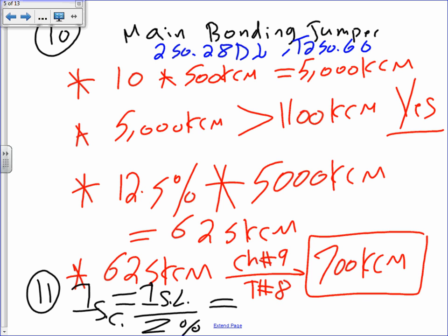What was the secondary line current? It was 2777, right? I have a 2, a 7, a 7, and a 7. Divide this by the impedance, which is 4%, in decimals 0.04.